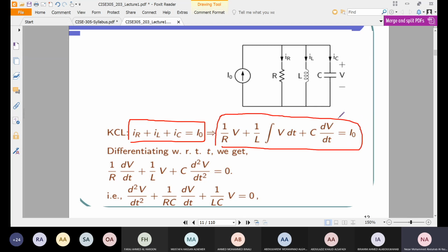And this we call the model, guys. This is the model. This is the solution to the problem. This is the model of these circuits. So by applying Kirchhoff's current law, I get the model, and this is the equation of the model. Sometimes we need to simplify the problem more by taking the derivative, because I want to eliminate the integration here. I might take the derivative with respect to time. We take one second derivative, so we have another solution. So this will be the model. Until here, you will get full mark. So this is what we mean by the model.